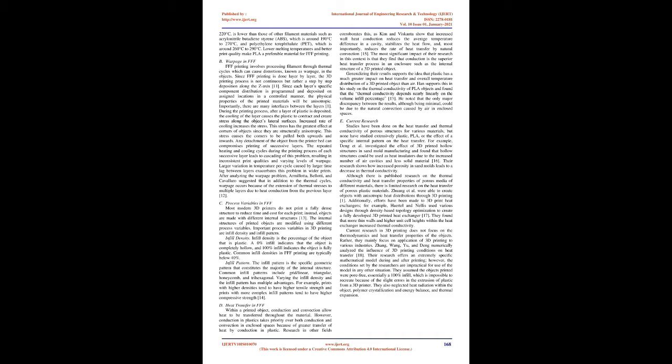The repeated heating and cooling cycles during the printing process of each successive layer leads to cascading of this problem, resulting in inconsistent print qualities and varying levels of warpage. Larger variation in temperature per cycle caused by larger time lag between layers exacerbates this problem in wider prints. After analyzing the warpage problem, Armillata, Bellotti, and Cavallero suggested that in addition to the thermal cycles, warpage occurs because of the extension of thermal stresses to multiple layers due to heat conduction from the previous layer.